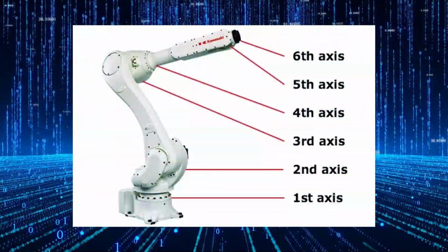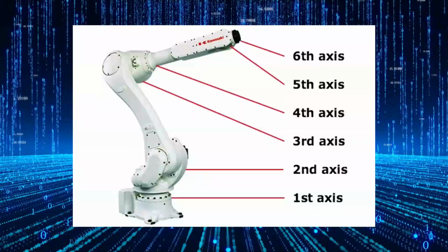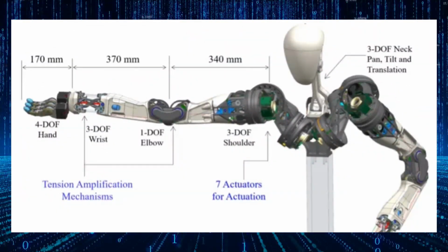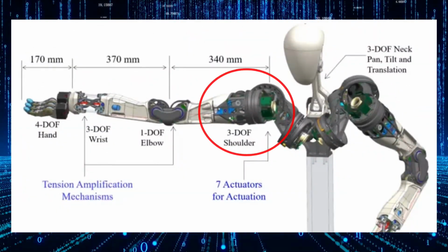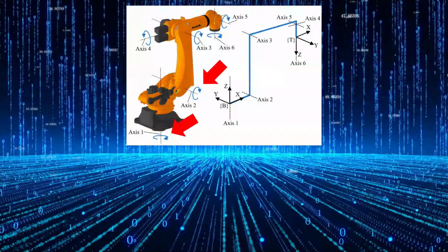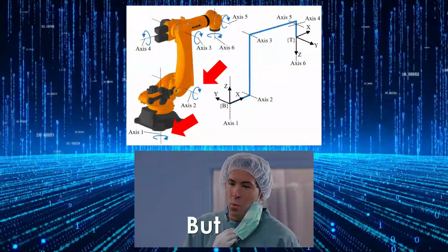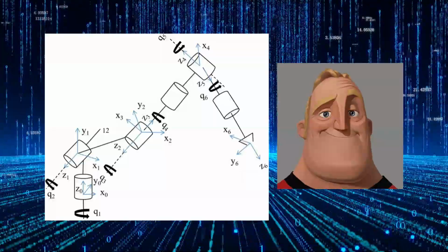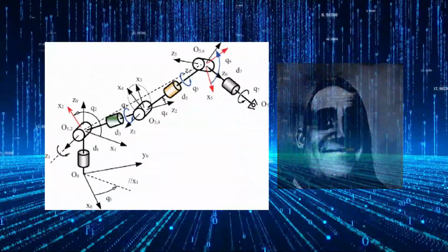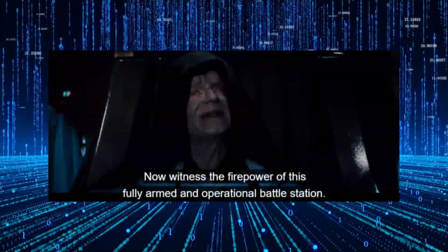Now, many robotic arms typically have 6 degrees of freedom instead of 7 like the human arm. The reduced degree of freedom is in the shoulder, where the robot will house 2 motors instead of 3. But why? Simply put, 2 degrees of freedom are easier to work with and often suffice for the movement needed for a fully functioning robotic arm.